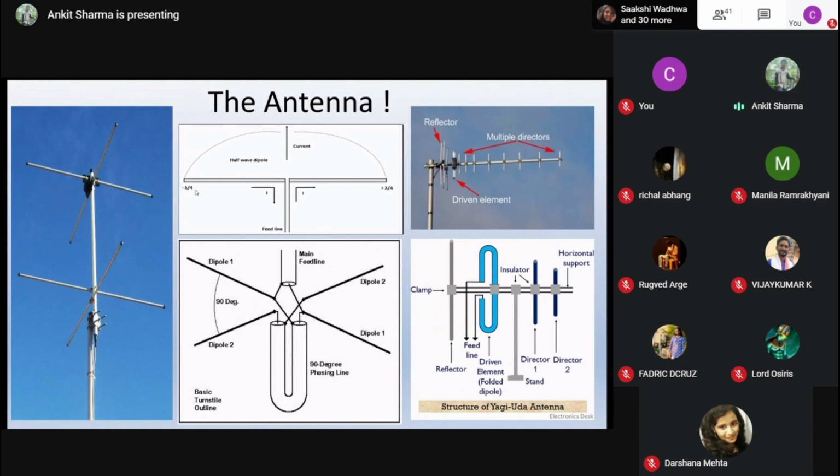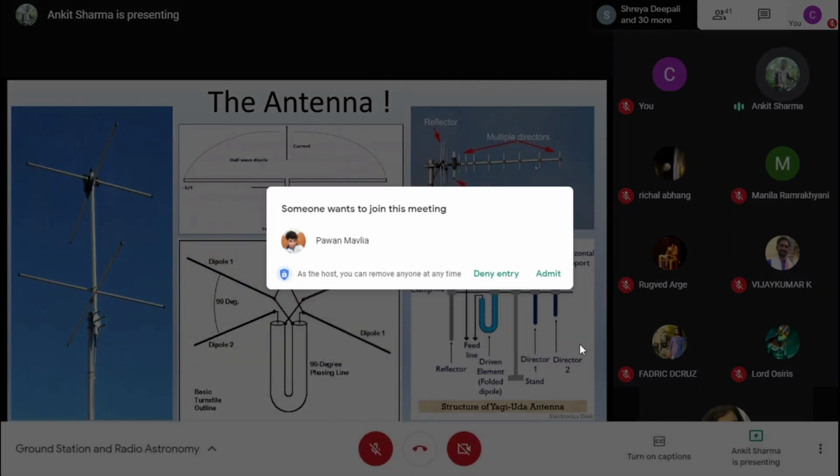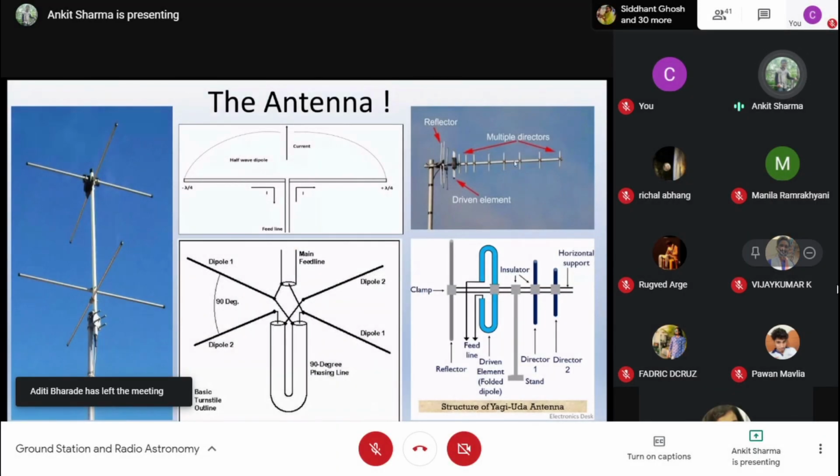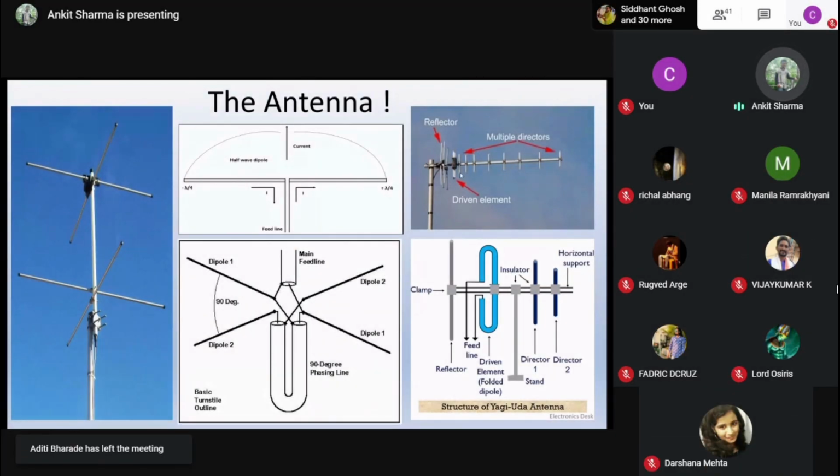We have here the Yagi-Uda antenna. Yagi-Uda is quite famous; you may all have heard about it. It has a reflector at the back, and in the front it has the directors, and we have one feed line, which is a folded dipole. So these are Yagi-Uda antenna diagrams, which you can relate to any Yagi-Uda that you might have seen. The lengths are subjective to frequencies, so you have to calculate them. There are calculators all around. You can Google it, or search in books as well.